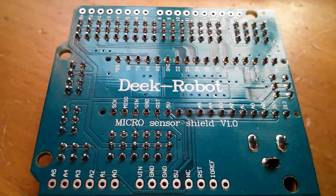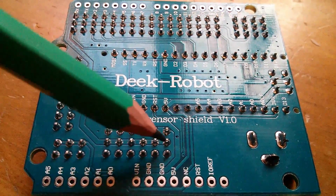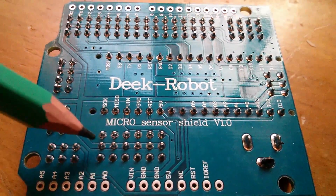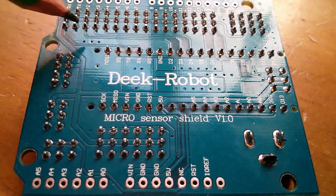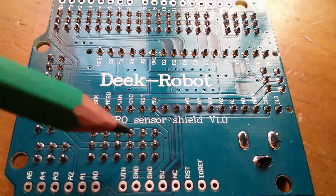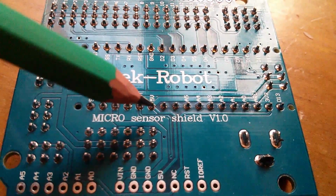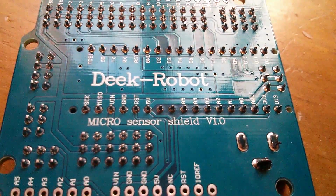So let's have a look at the back of the board. So this looks pretty easy to do actually. This line coming down here runs through the VCC, the red connectors for the 6 analog pins, and then it runs up here through all the digital VCCs. So it should be relatively easy to cut the track at this point here, just put a small break in there, and then route these 6 connections round to 5 volts at this point, which is the output of the analog regulator on the Nano.